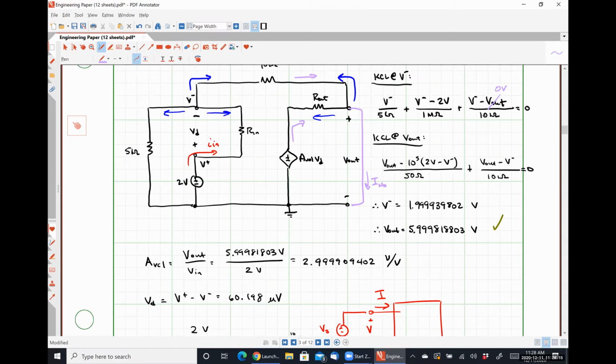Perfectly reasonable if you don't follow what's going on. I'd rather stop and talk about it than go on while you guys are just sitting in the dark. Any questions about what I'm about to do? Okay. So I no longer need to do anything having to deal with this second equation down here because everything is sorted out, right? I know that V out is 0, so these guys really don't apply. So I'm just going to solve this guy for V minus, which will let me determine VD, and then that's all the information I need to be able to solve for my Norton current.